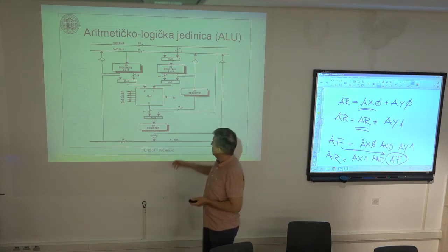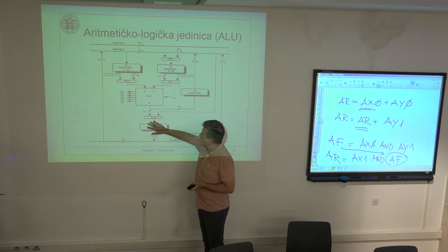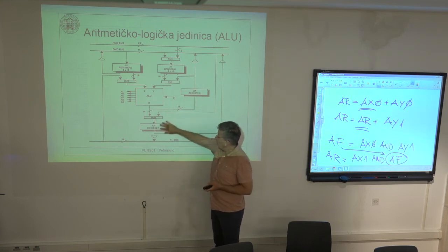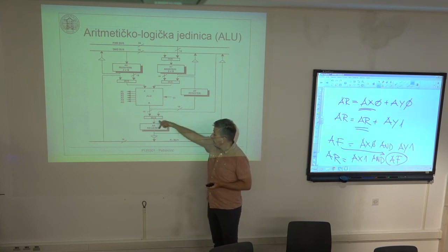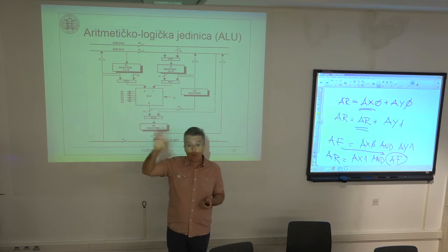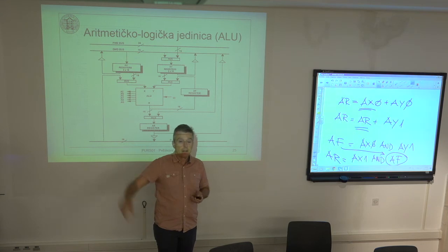Okay, going further, we have described the result register and the feedback register. You can also write the value directly into the AR register by reading some value from memory. For example, AR is the data memory addressed by pointer I0.